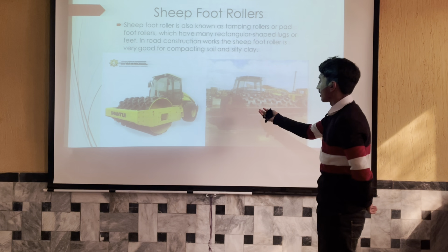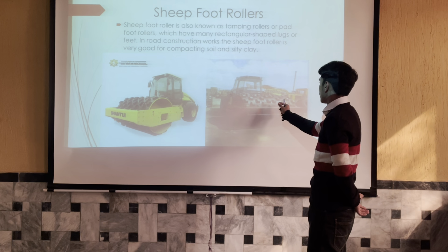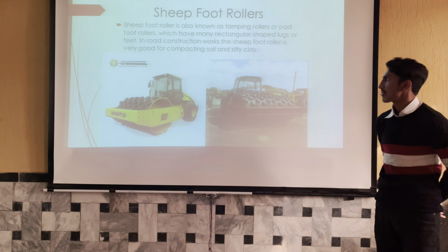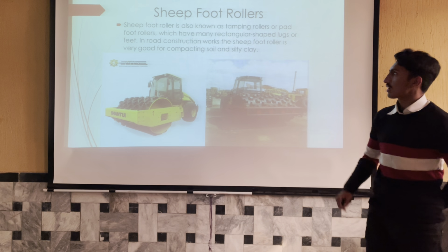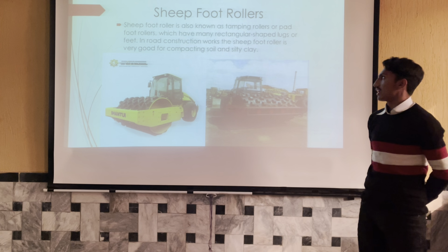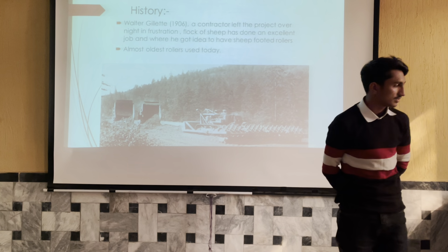You can see that there are different types of legs or pins, and different sizes and types of feet. They are basically used for compacting soils in embankments and roads, and normally we use them for compaction of soil.